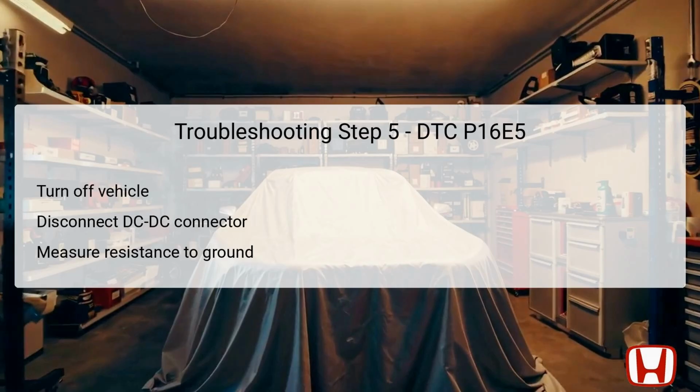With the connector unplugged, use a multimeter to measure the resistance between test point 1, the female terminal number 1 on the DC-DC connector A, and test point 2, which is the body ground. This test determines whether the resistance is above 1 megaohm, 1 MΩ. If the resistance is adequate, the analysis continues. If not, subsequent steps will focus on repairing any shorts or opens in the wiring.